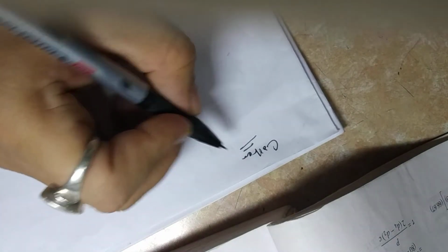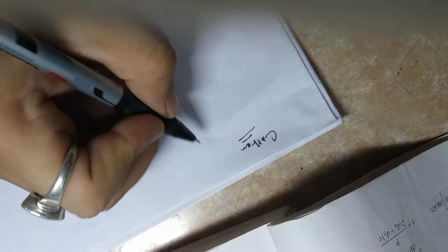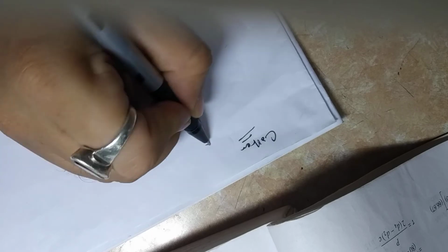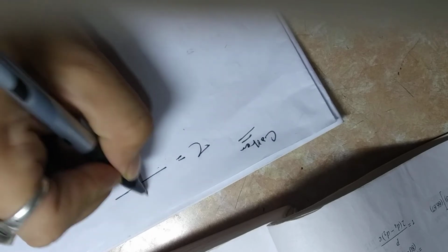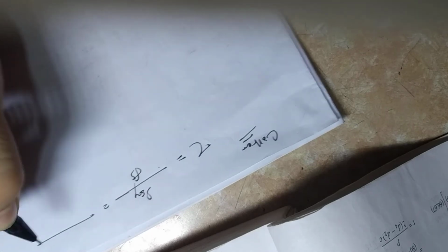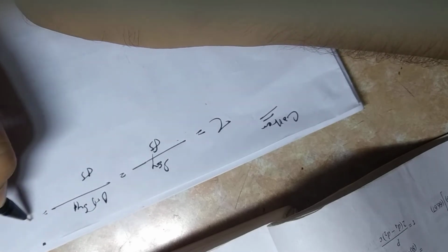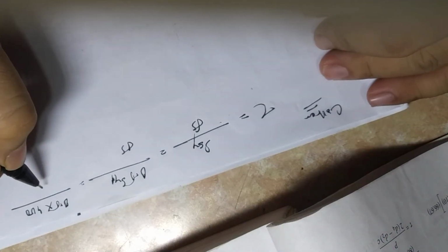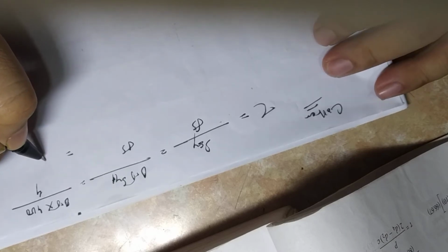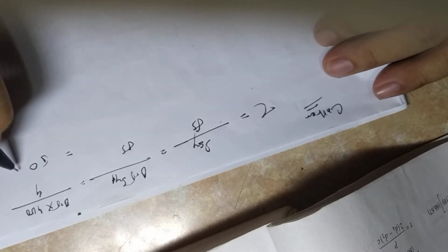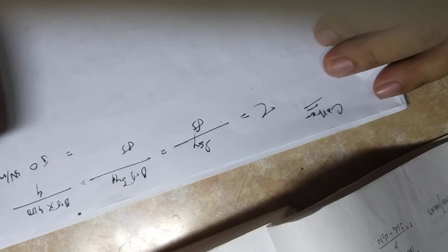Now, for the Cotter you have to find out that since there is a shear failure, so S_SY by FS, 0.5 times S_YT by factor of safety. This is 0.5 into 400 divided by 4. So from here we find out this is 50 Newton per millimeter square.